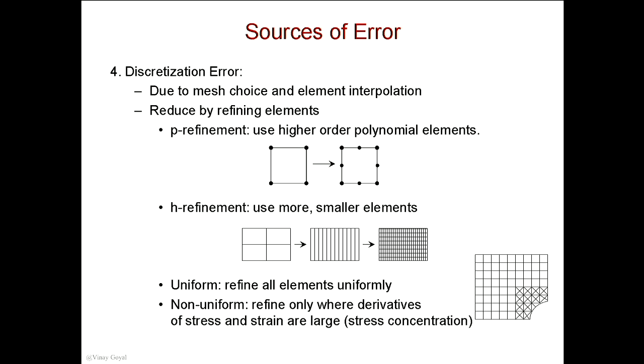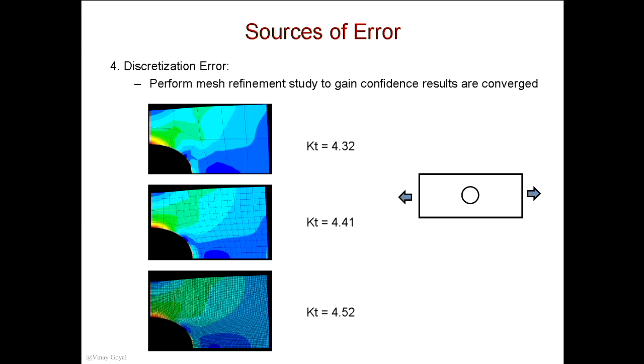So if I have an element here, I'll show you an example coming up. For example, here, clearly this element has a completely different stress from these elements. And so, therefore, you definitely want to refine the mesh to the point that you have multiple elements in the same color, right? Basically within 10%. If you can do that, you basically have a nice, converged mesh.